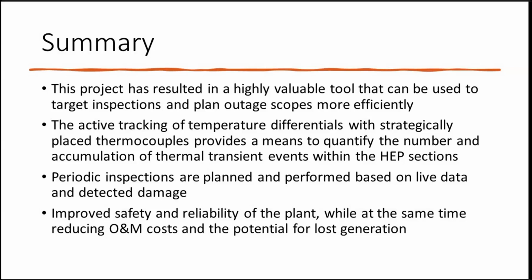I actually worked with Bob Anderson when we did our first round of attaching tube skin thermocouples at one of our power plants, and he really helped out, him and EPRI as well. They have some reports that show you photos and the attachment techniques, but it's capacitance discharge welding, and it's just a small battery-powered unit that you can take in.